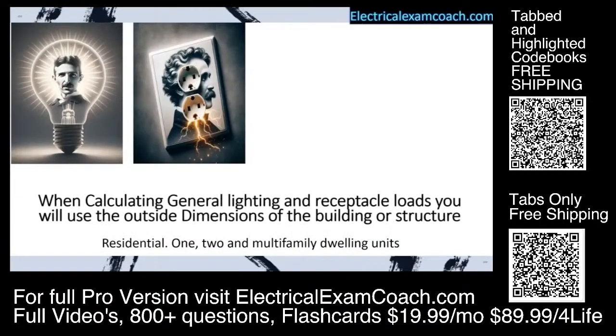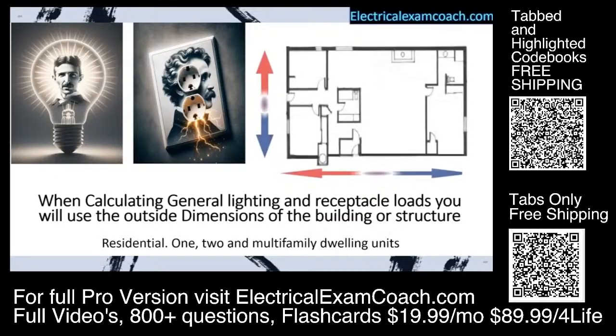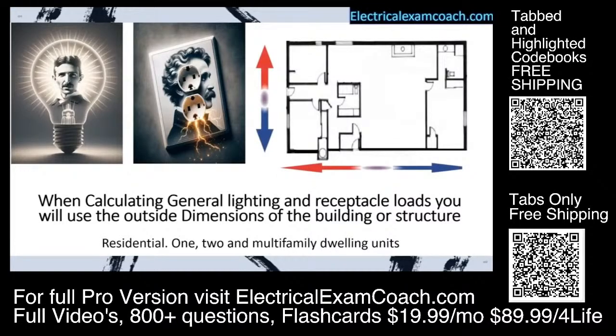When calculating our general lighting and receptacle loads, we will use the outside dimensions of a building or structure. So we're going to measure from the outside of the building, both directions, do our multiplication, and that'll let us know how many square feet we have to multiply by.